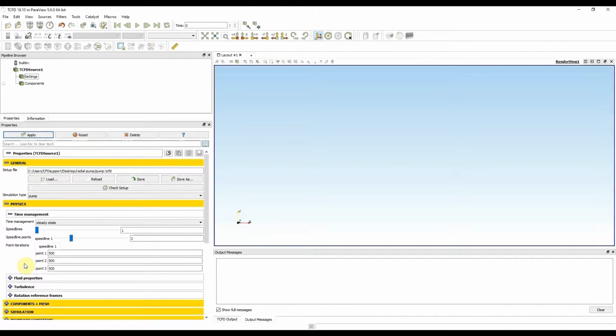If you have a very large number of iterations, but the case converges much faster, then it can stop because of the convergence check, which I will show in a later section. Also, this case is incompressible, and if I computed a compressible case, it always needs more iterations. So a good starting point for incompressible simulation is like 1000 to 3000 iterations, and for a compressible case I recommend much more, like 4000 to 7000 iterations per 1 point. This is everything in time management, and I can continue to fluid properties.